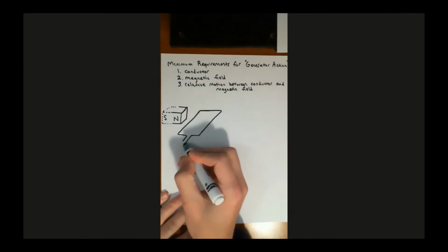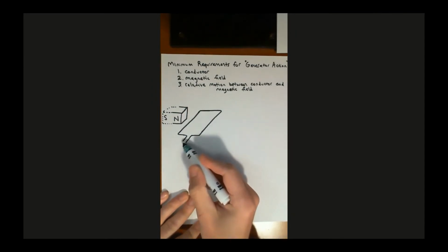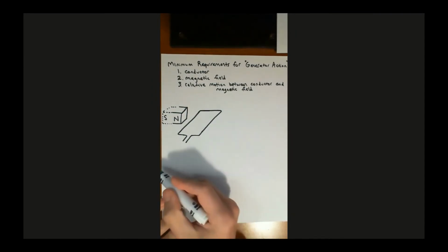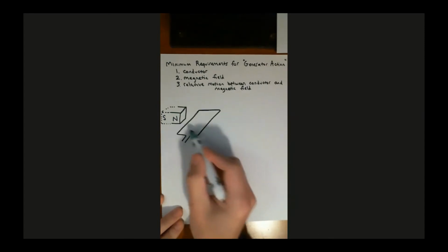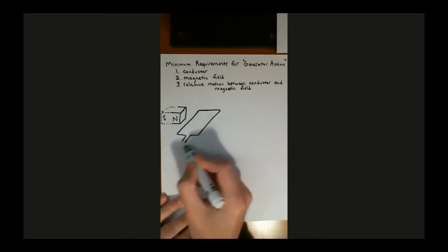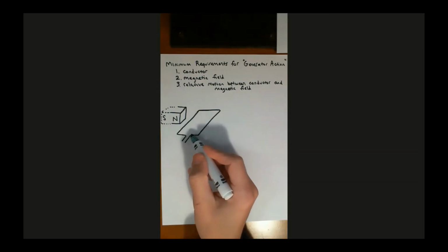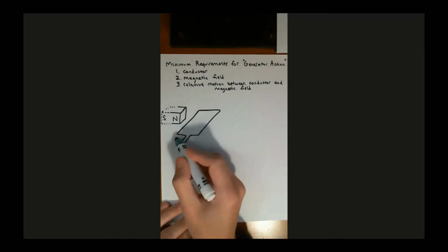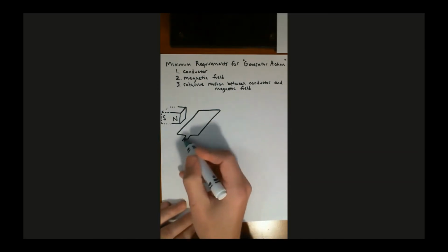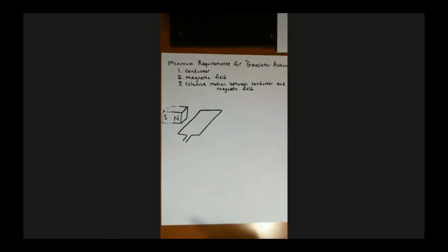And then these are my outputs. We'll talk a lot more about how you get the induced voltage out, right? Because this is gonna rotate. I haven't said that yet, but this is gonna rotate. We're gonna call this coil of wire an armature, and this is going to be rotating. This is our input shaft to our generator. It's coming in here and rotating this armature, and that input shaft comes from the output shaft of the turbine.